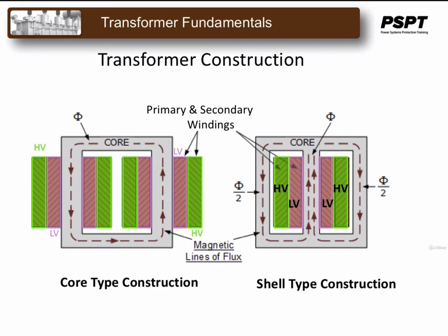This means that the magnetic flux circulating around the outer limbs of the core of the transformer construction are equal and one half the total. As the magnetic flux has a closed path around the coils, this has the advantage of decreasing core losses and increasing overall efficiency.